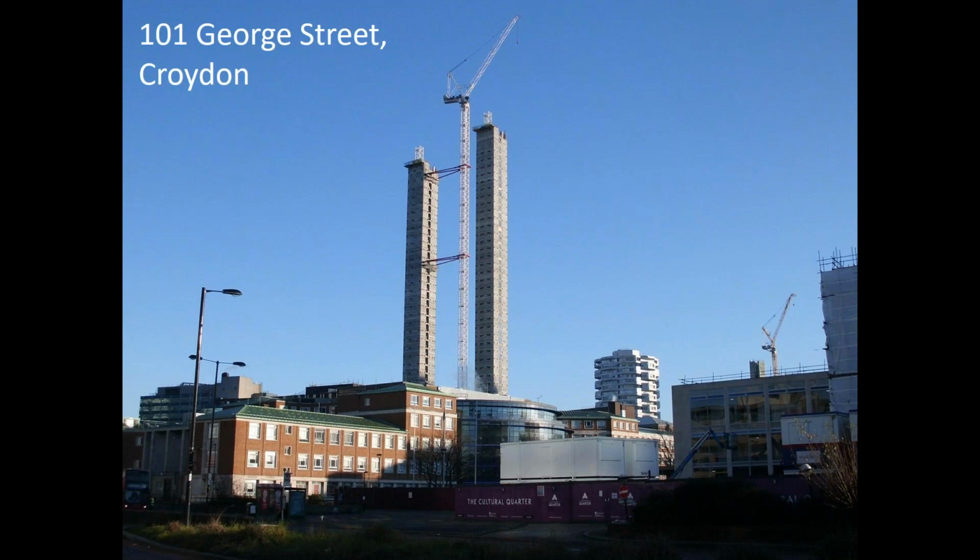And the other thing is, because you've got 2 buildings next to each other, another potential design check would be interaction between the 2 cores in terms of wind loading, potential channeling of wind load from one core onto another, meaning that potentially the overall wind load on one core might be higher given the proximity of another core than would be the case if it was just one single standalone core.